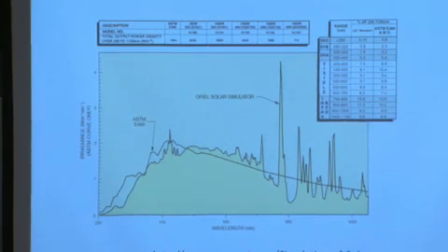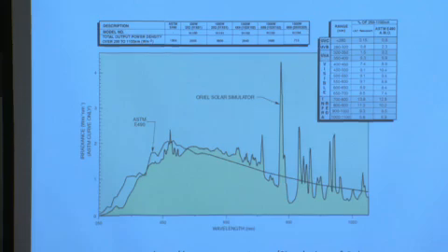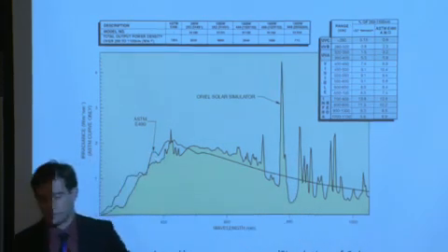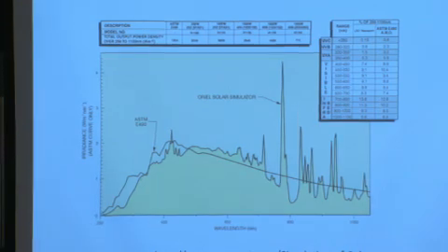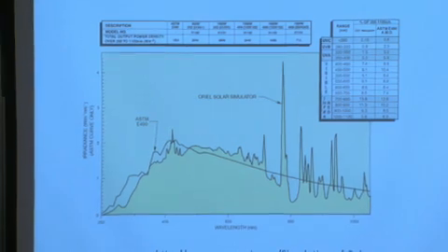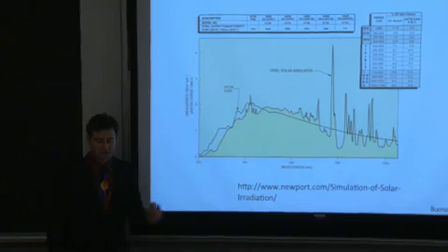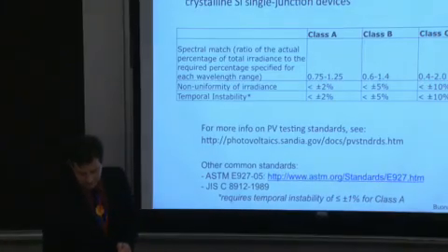This is of some concern if your device is particularly sensitive to a spectral region where those might be present. So it's not a bad idea to take a measurement of your light source and actually understand how it matches up against the ASTM standard spectrum.